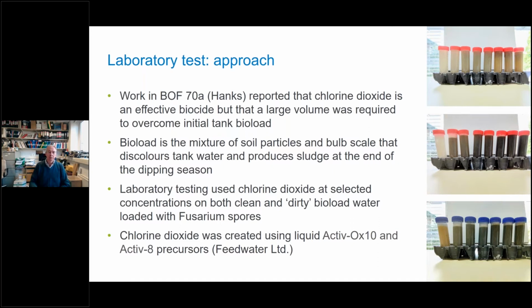And our first step was to do laboratory testing at selected concentrations of chlorine dioxide on both clean and dirty water systems loaded with fusarium spores. And it was really at this stage to see what was the effect of concentration and what was the effect of clean and dirty water. And at this stage, we were using a liquid combination to generate our chlorine dioxide. And the pictures on the right-hand side show you just how much variation it's possible to get in tank waters.